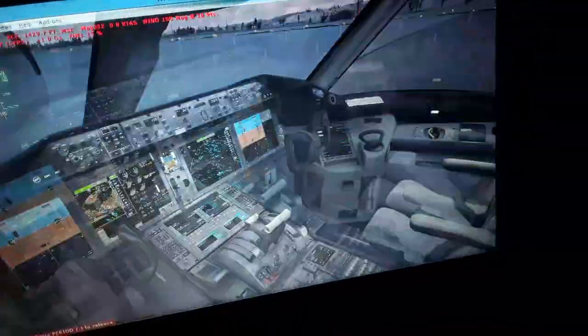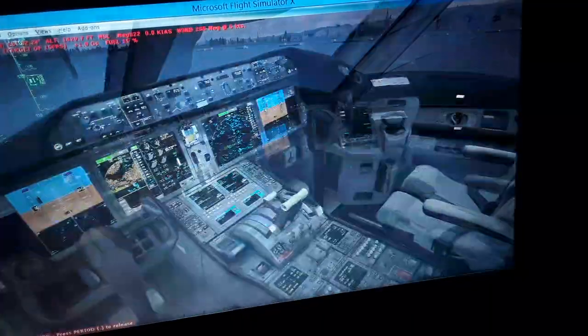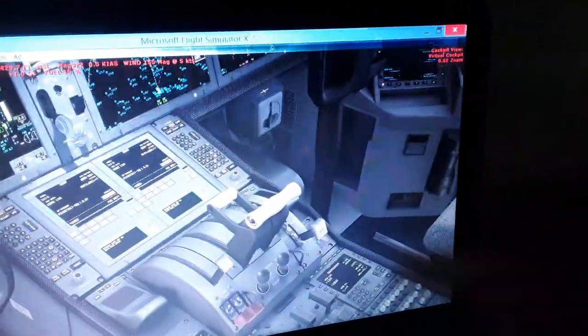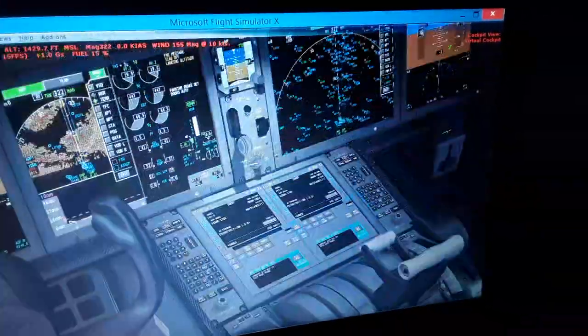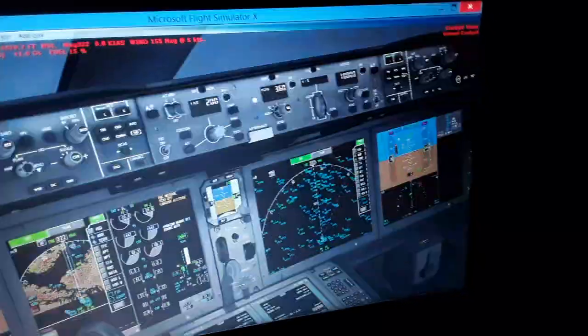Also to keep the balance in flight. And you have also the auto trim function. So I'll show you the auto trim, what it's doing for the Airbus, for the Boeing actually. You can disconnect the automatic trim and use the manual. If you have failure, you do that. So I will show you also a couple more systems of the aircraft.